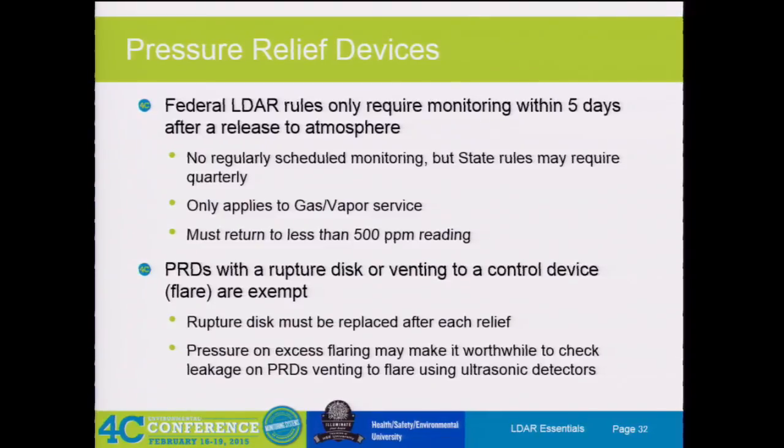Well, you also want to make sure too when they're doing that, all of a sudden I didn't see 50 visuals happen in about 33 seconds. That's great. No, because that means that they just didn't do it. So you want to be able to document timestamps and see. But some folks, we've had it where when we ask them for it as part of an LDAR audit, they just bring us a stack of written papers from their operators that are like this big and go, what week do you want?